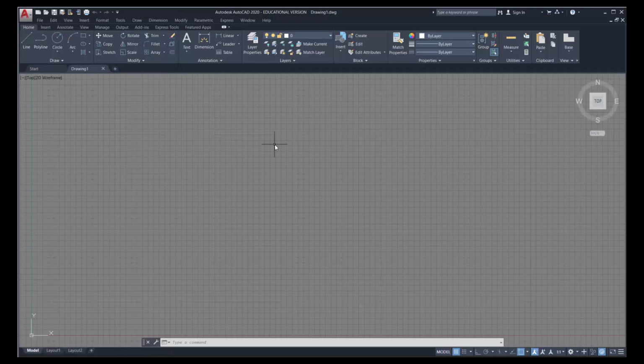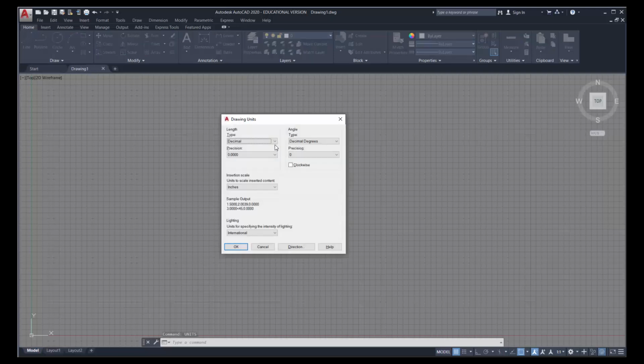We're going to use architectural units. So right at this point, just simply type in units, and you should see it actually appear on your screen. It also automatically shows any other similar types of commands, but we've got it correct, so we'll just press Enter. We're going to be working with architectural units from here on in throughout the projects, but this is a good practice to get into. As a review, precision refers to how it's going to be displayed when we dimension.